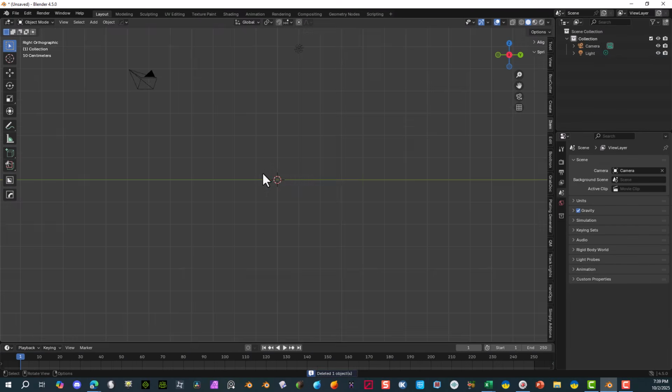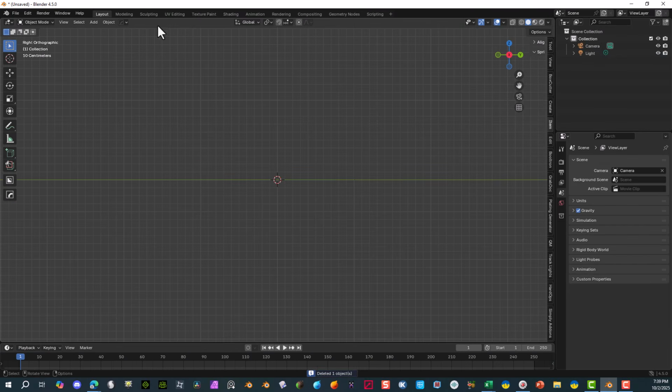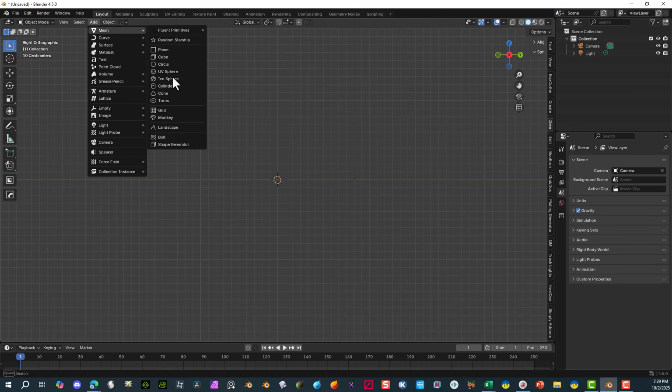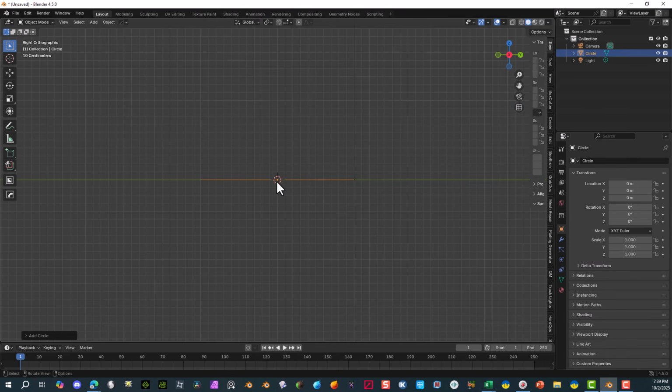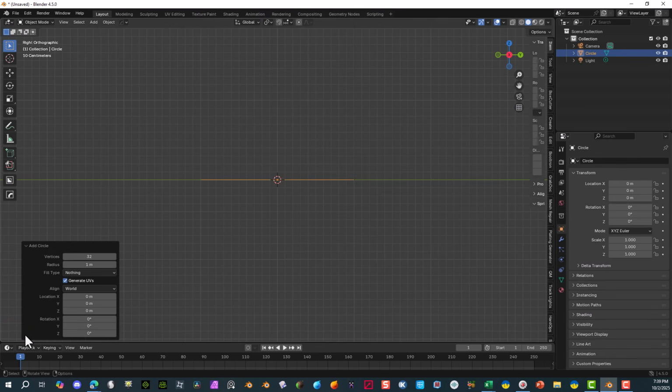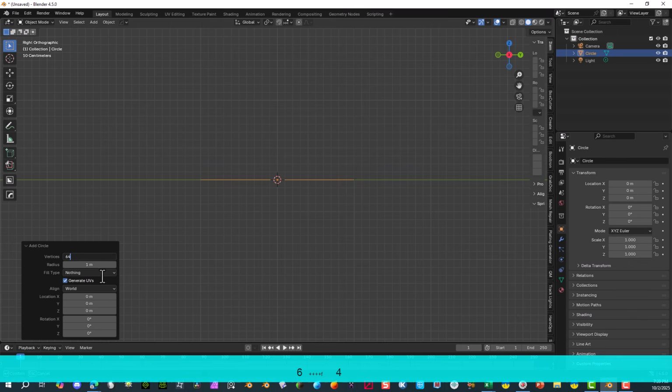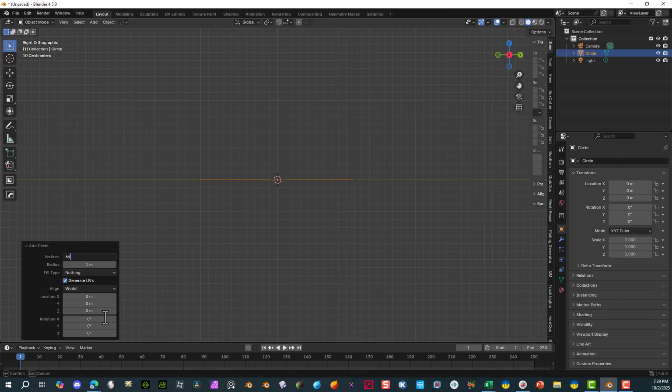And I'm going to start off with kind of zooming in a little bit. Some things I'm going to do here is basically work with actual line shapes just to make this a little bit easier. So I'm going to go to the mesh, go to circle, and click on that. This is, of course, the wrong radius or turn area. So I'm going to go in here and actually change this also to 64 points. And this is going to be an n-gon object, just for your awareness. I'll be showing more stuff on how to do quad-based objects.